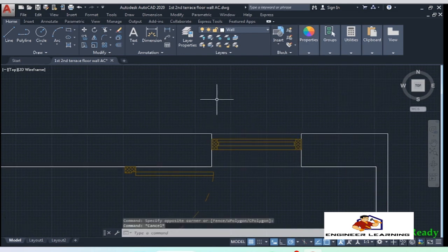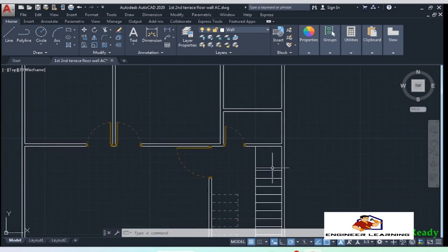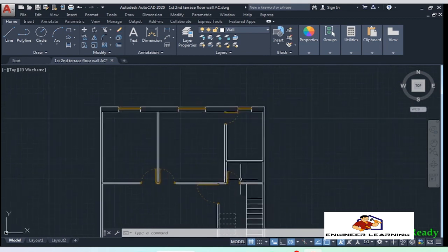For the small common bathroom, we cannot place the window up here. A staircase is near to it. It will be inappropriate. So a small exhaust will be placed in the false ceiling of this bathroom, whose pipe will lead to the rear side of the house.